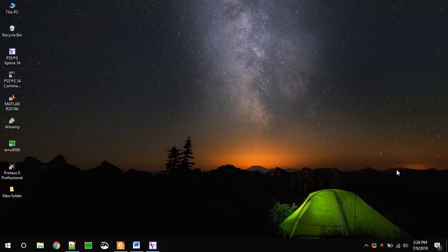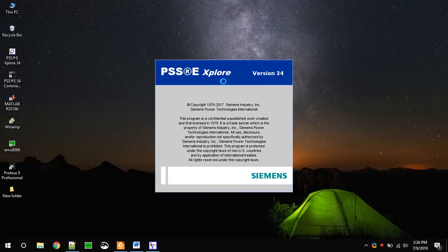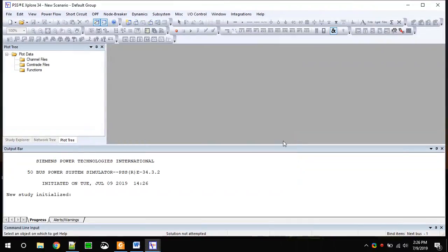Hello everyone. In this video I'll show how to perform dynamic simulation in PSSE software, and also I'll simulate a generator tripping condition and automate the whole process using Python in PSSE. So let's get started. For the software I'm using PSS/E Explorer 34, which is a freeware version given by Siemens